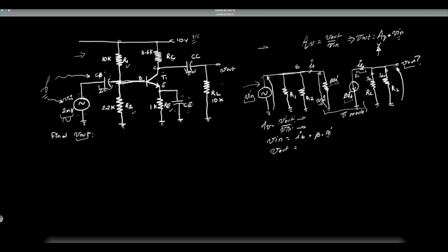Notice the direction, the relative direction I picked for V out, right? So I'm acting as if this is a DC voltage here. So that means this is negative, positive, and this is just so I can have my bearing. If my current is in this direction and my voltage is in this direction, then they're not opposite to each other. So that means this is a negative value based on Kirchhoff.